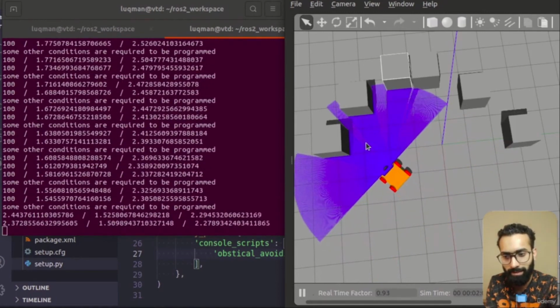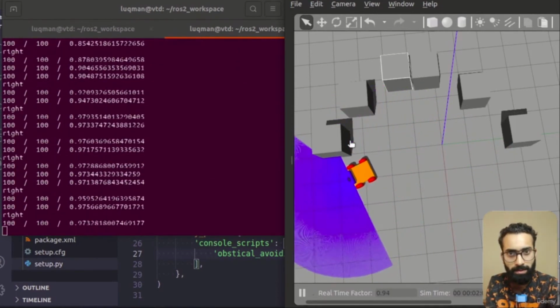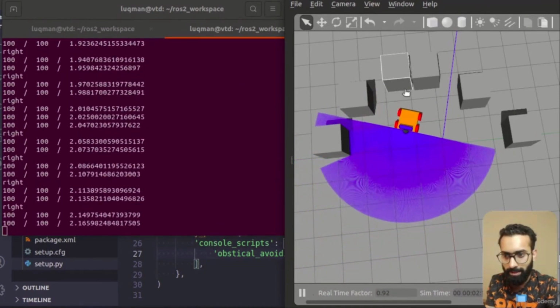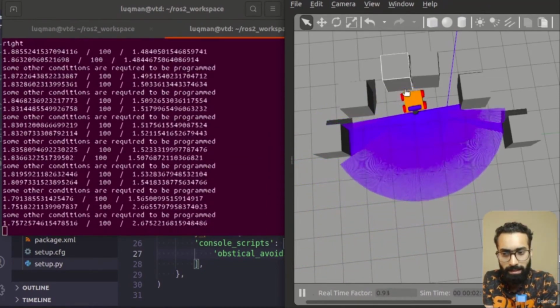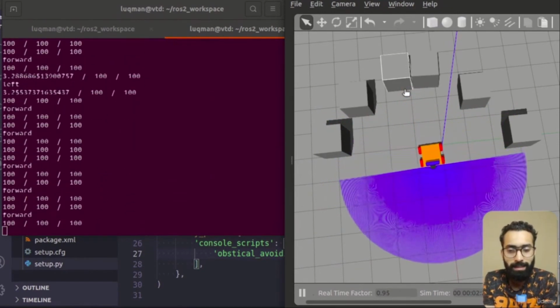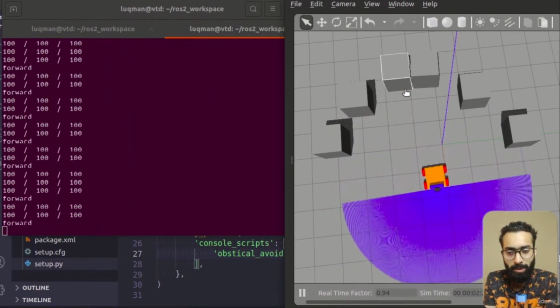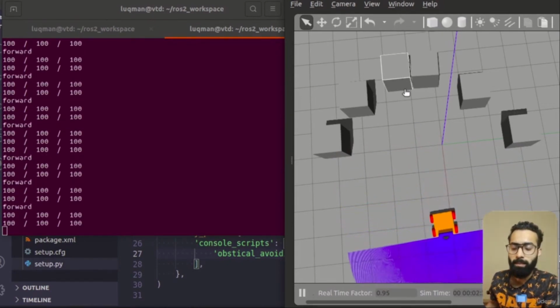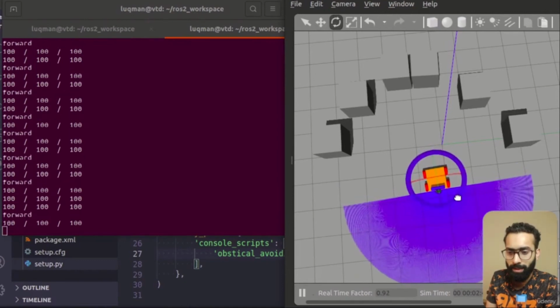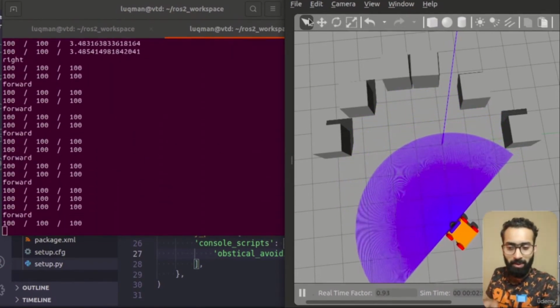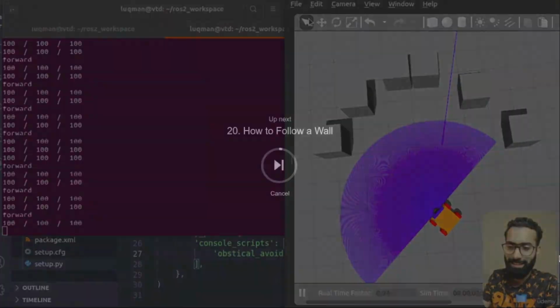When the object is not in the left and right region, the robot does not stop. Okay, in the mid area there is no condition applied. This is the point where you can add certain conditions as it is going to hit. The condition the robot is following right now is that unless all of the areas are clear after going reverse, the robot is not going to stop. When all of the areas get clear after going reverse because of an object covering all of the areas in front of it, then it will move. So this is sort of a problem. You can solve this by adding 2 to 3 more cases, and it would be very fun. So that was awesome. Our robot is actually avoiding the obstacles.